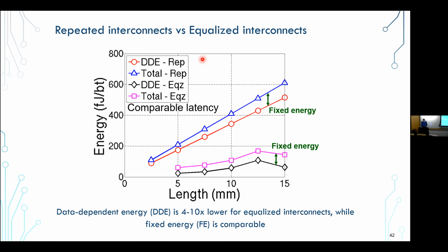So this is a little bit of the comparison. When you have these types of channels, some energy is proportional to data. That's what switches through the repeater. But for example, clock energy on the flop that we had is not data proportional. It happens at twice the frequency, right? The data density on average is 25% switching, clock is 50%.